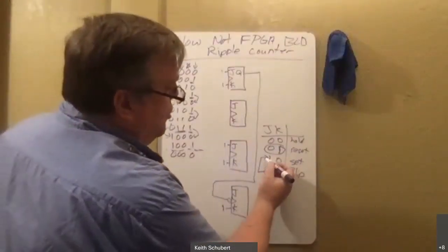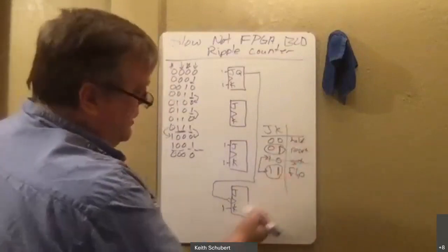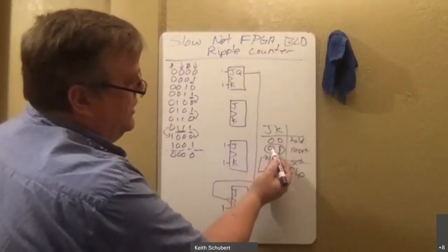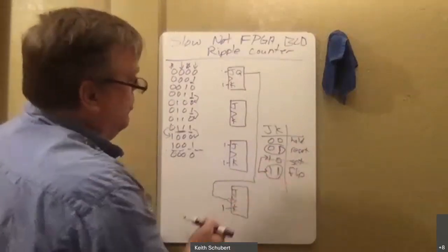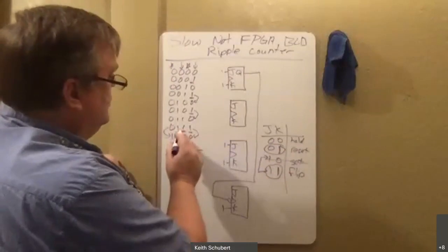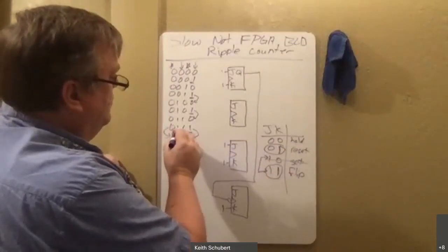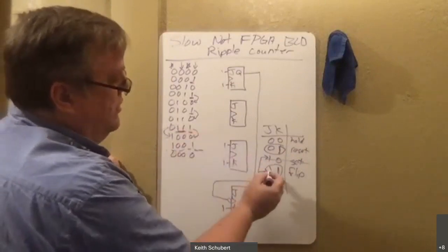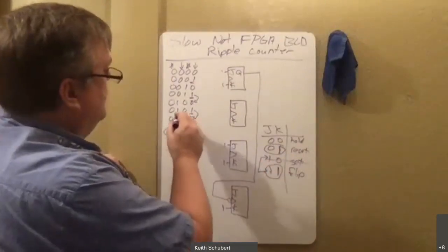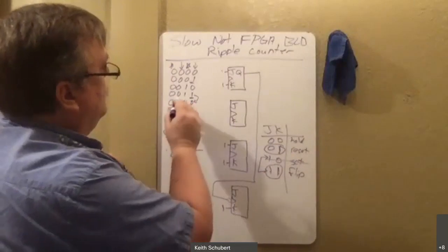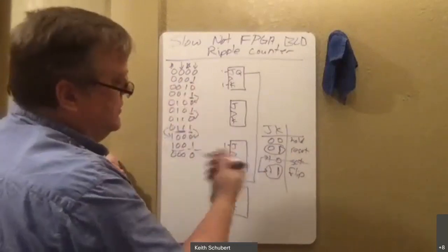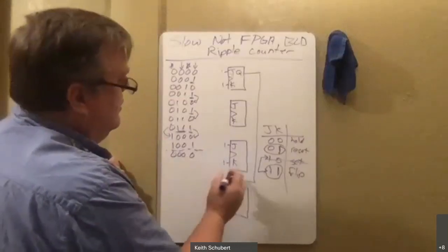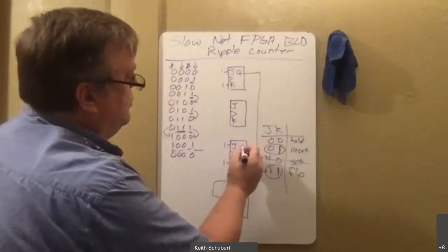So I don't pick this, just so I can have both of these ones have K. And then I notice J is either a 0 or a 1, which is the same as what if I ANDed these two bits together? 1 and 1 would give me a 1 coming in. In all other cases, when the transitions happen, I don't have both 1s, which means I get a 0. So my J value, I'm going to take the previous two Qs.